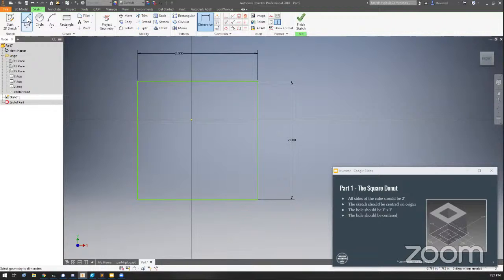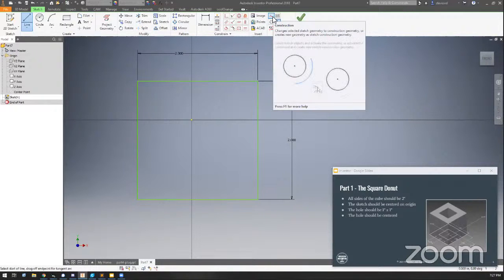It's something that's used as a reference. Okay, so if you click the line tool and you draw a line, you'll see that it's a green solid line, and you can move this thing around and draw. But this would actually be a piece of the sketch. We don't want an actual piece of the sketch to build on. Instead, we are going to select line, and then in this corner, you see there is something called construction.